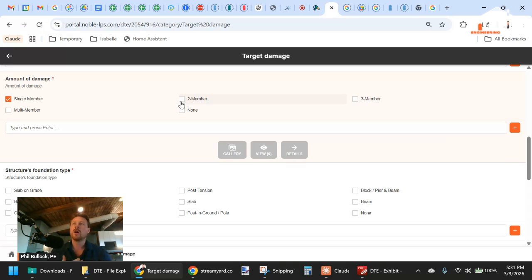And so we also want you to put some weight on the damage. That sounds weird. It sounds like I'm asking you to be unsafe, but typically what we'll see is bowing and deflection in the areas where we have this damage. And I want you, as safely as you can, to approach the damage condition and decide whether or not you see an active bowing condition with you putting your weight close to or at the point of the problem.